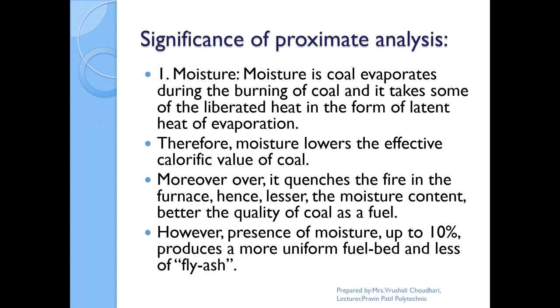Why are we going to perform this proximate analysis? Why are we determining the moisture? Moisture in coal evaporates during burning, and it takes the liberated heat to form latent heat of evaporation. Therefore, it decreases the effective calorific value of coal.